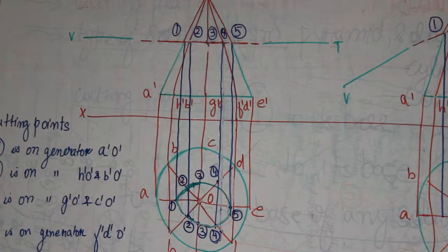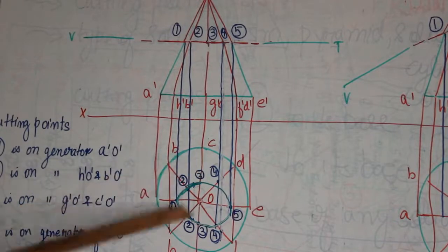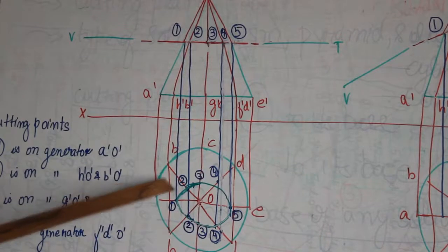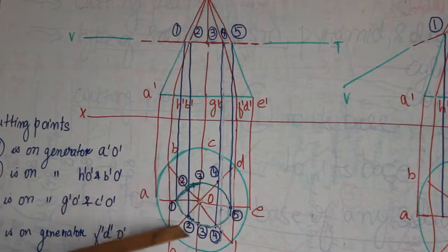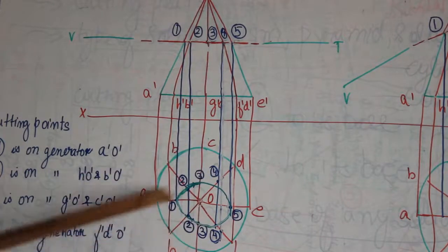You will have to use a light pencil, that is a 2H or 3H pencil, to make the hatching lines, and the hatching lines will be inclined at 45 degrees, with the spacing between each line around 2 mm to 3 mm. The lines should be uniform and they should look good in the section.